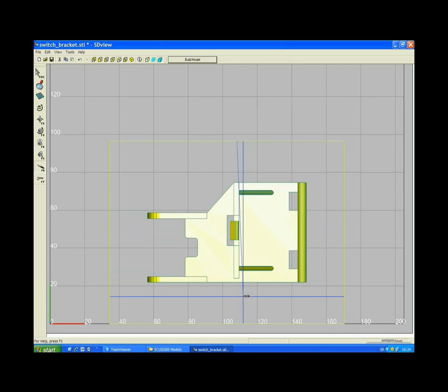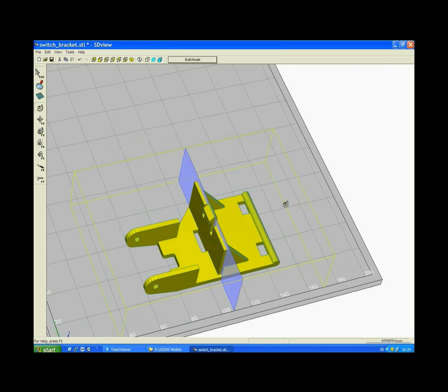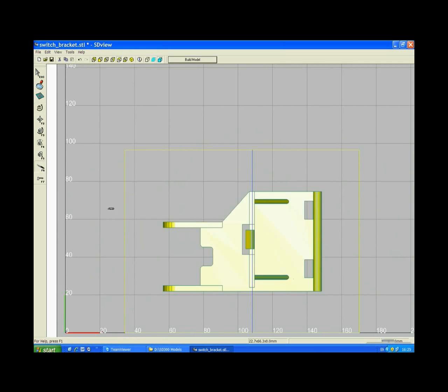Using the Shift option, we will snap it vertically and snap it to the bounding box. You can now see that we have divided the support material around our geometry into two areas, the first area and the second area. Now we will place peeling cuts through the center of both smaller walls. Again, we will snap the peeling cut horizontally until we reach the first peeling cut.